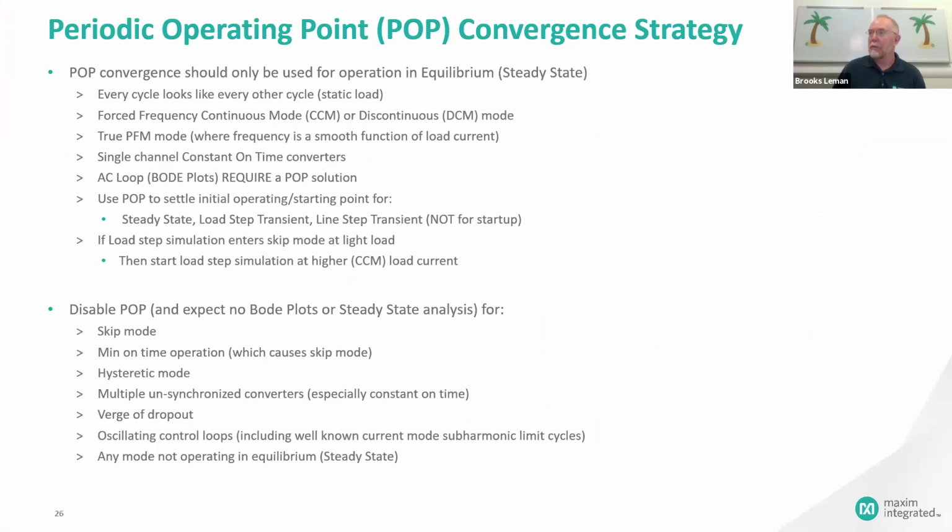And this is the periodic operating point strategy. The POP convergence should only be used for operation in equilibrium, okay, or steady state, where every cycle looks like every other cycle.